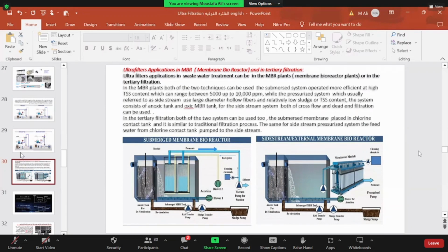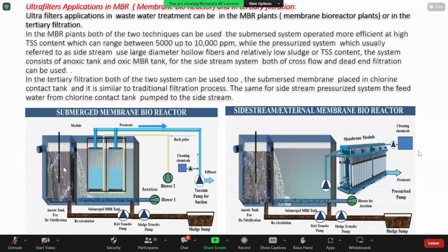The wastewater comes to a screen for the removal of coarse waste, and then goes to the anoxic tank for the removal of nitrate, where anaerobic bacteria use nitrate to remove oxygen and convert everything to nitrogen gas, which will be expelled to the atmosphere in the next tank. The detention time for the anoxic stage in the wastewater treatment plant can be between 1 hour to 2 hours.